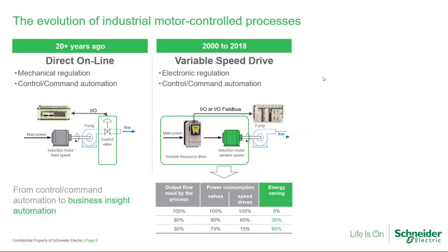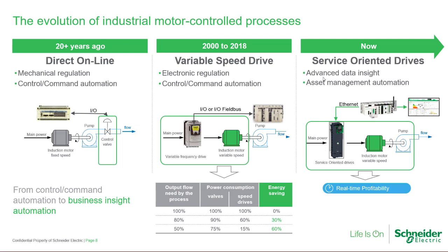When we look at the transition of motor control over the period of the last 20 years, you can see that we've gone from traditional DOL starting, where the pump is mechanically controlled, the valve controls the flow, through to the VSD controlling the flow, but then upstream standard IO devices controlling it, to a service-orientated system where now communications between the pump, the drive, the monitoring system, and cloud-based services give you access into real-time profitability, energy efficiency, and asset performance.